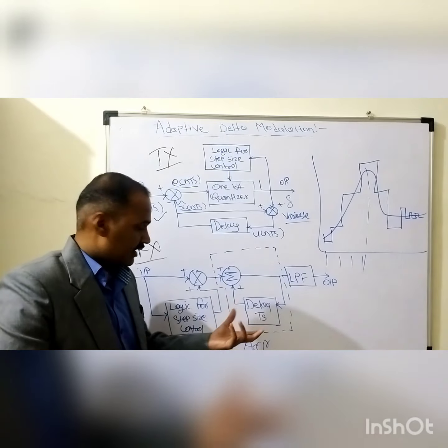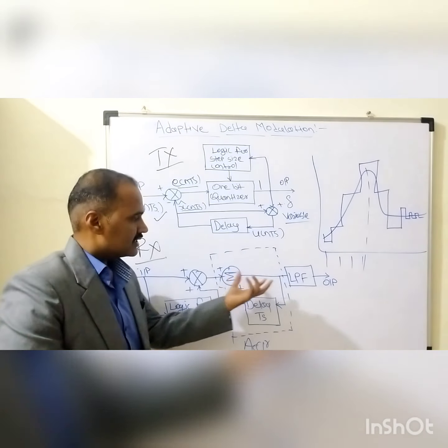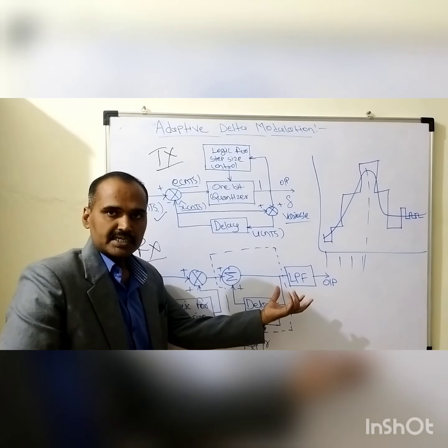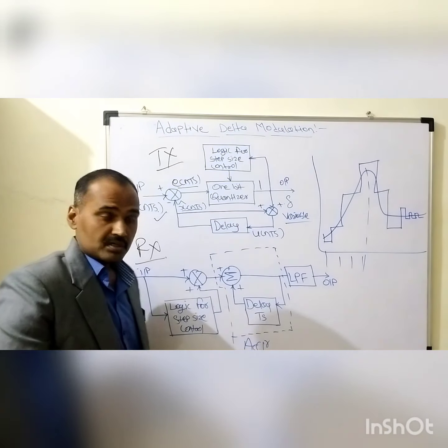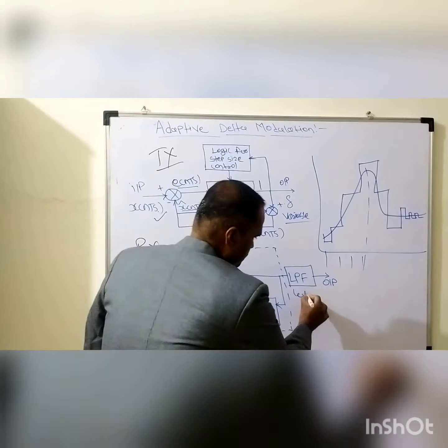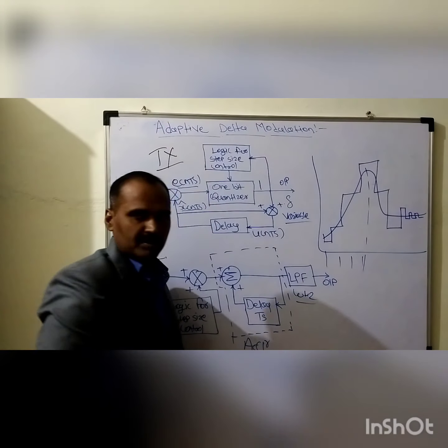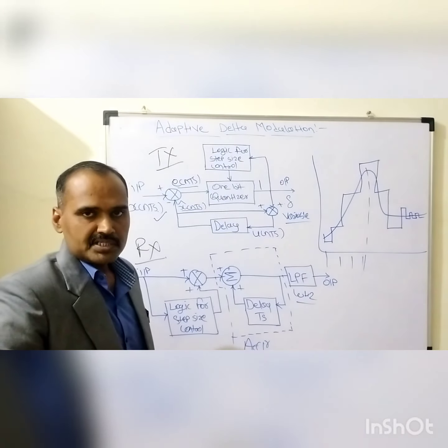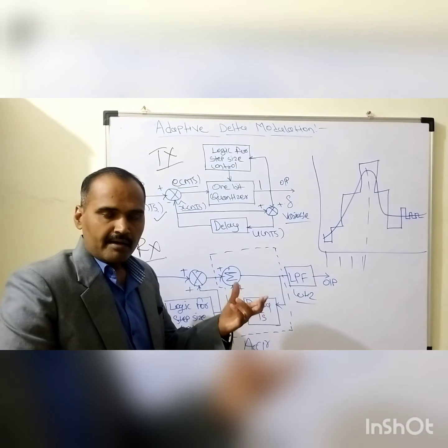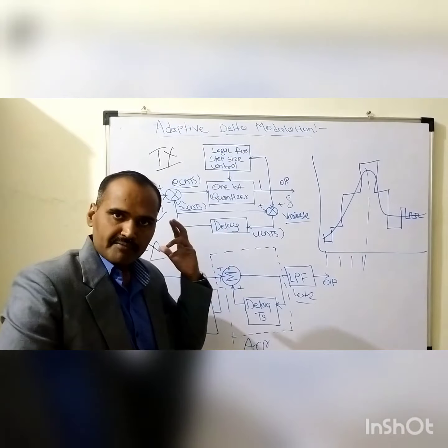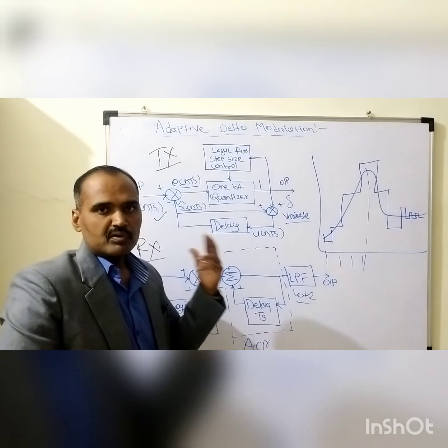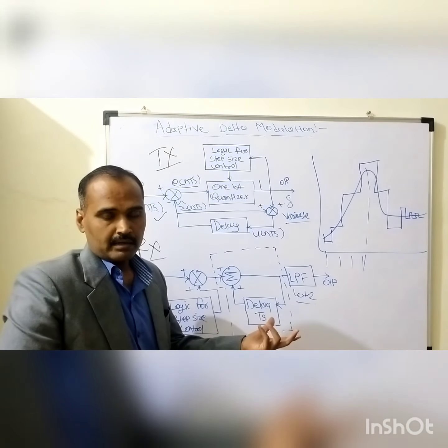Once that envelope is generated, this desired envelope of the staircase approximated signal is passed through this low pass filter, whose cutoff frequency is exactly equal to omega hertz, which is nothing but the maximum signal frequency component present within the envelope of this continuous time signal, which was given to the input of the sample and hold circuitry.